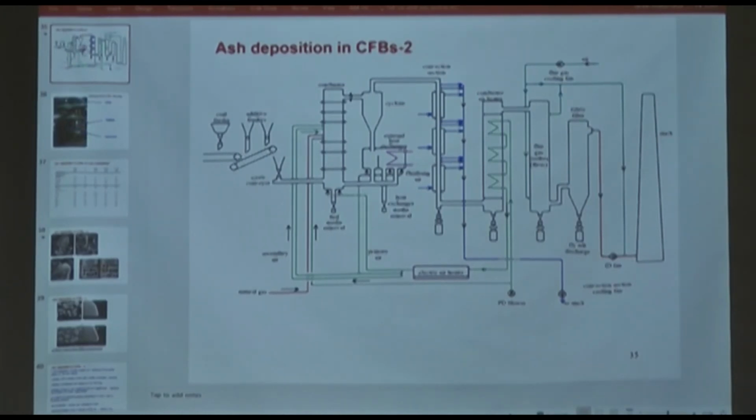Fouling, as I mentioned before, is easier to detect, because in tubes you can put thermocouples inside. If the inside temperature of the fluid, whether that's air or water, drops, then you know that fouling is building up, and temperature can only drop. So these two.